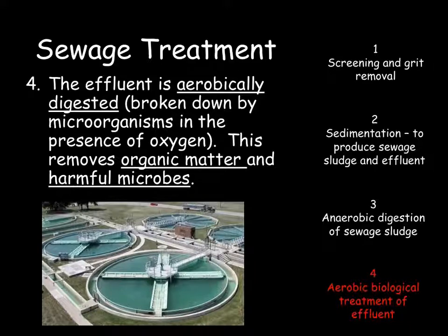In order for this effluent to re-enter the potable water banks, what we need is to then treat it for any additional toxic substances. So we might add chemicals in order to precipitate out the metals. We can carry out UV radiation or use additional membranes to clean this. We will then re-add chlorine to kill off the microorganisms.